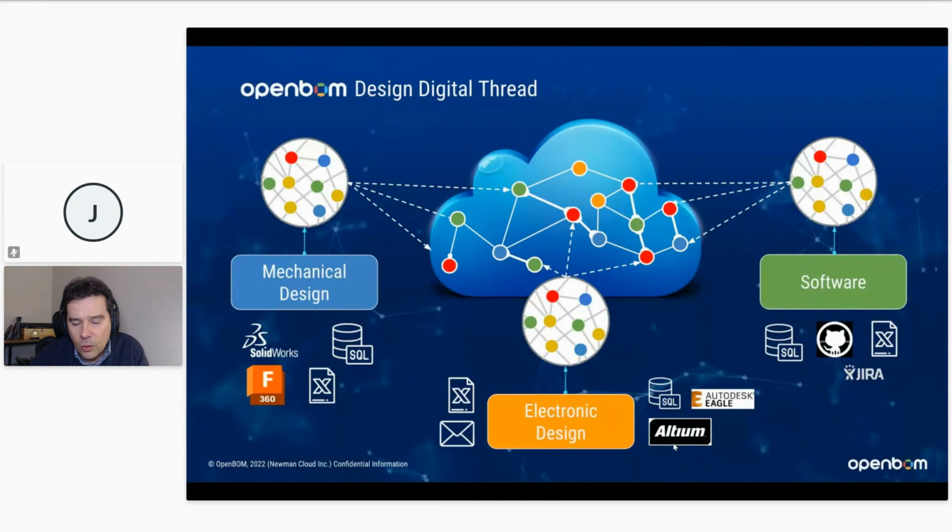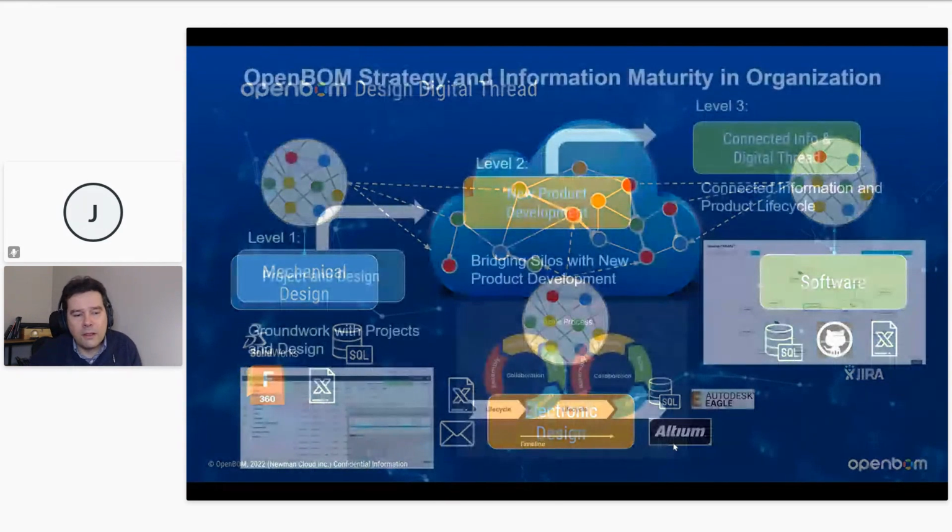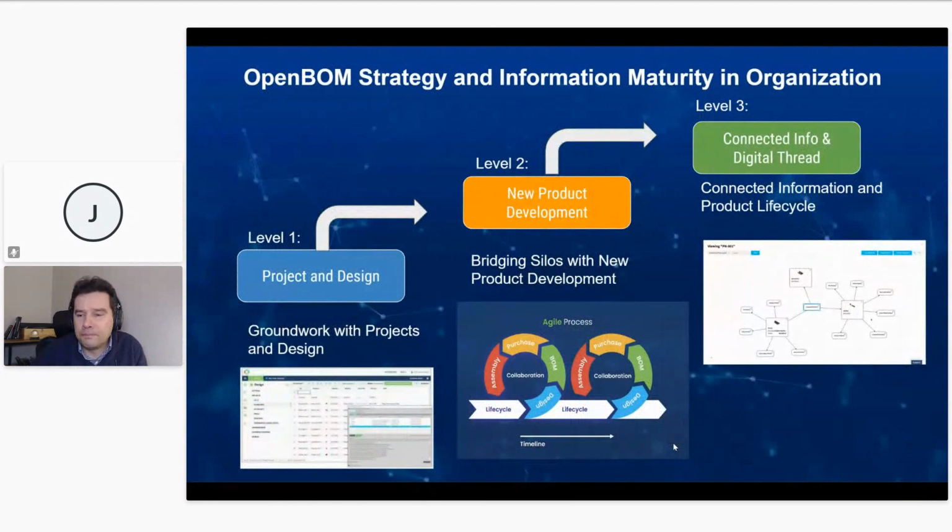So we see different stages of development. The first is the area of OpenBOM design projects. Here is where you can manage your design sources. If you are using tools that are file-centric like SolidWorks or Inventor, you can install a Windows component, the Workspace Manager. This will synchronize your files to OpenBOM, and you can collaborate with others, manage and synchronize changes, and prevent overrides with lock features.